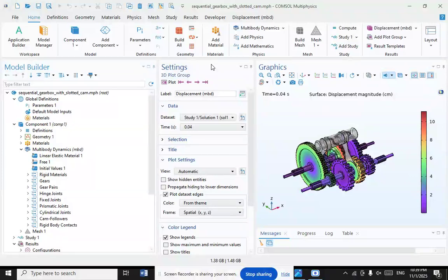And what about the usage? Most motorcycles use a sequential manual transmission. The rider controls the gear shifter with their foot, allowing their hands to remain on the handlebars. Gear selection uses a layout of 1 and 2, 3, 4, 5, or 6. For a typical 6 speed gearbox, it is set as 1 down, 5 up.